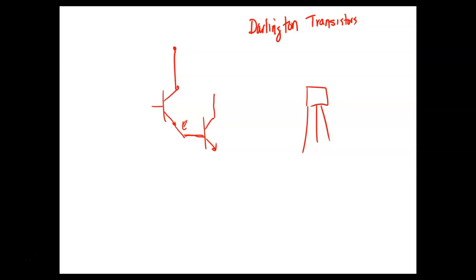We had a printer that used the Darlington pair to fire the hammer, and it was drawn as a regular transistor. So I pulled it out and I checked it with my ohm meter, and it checked bad. I put another one in there, it did the same thing, because the transistor was a Darlington transistor. So then I looked the part up and said, well, that's a Darlington, so that's why.